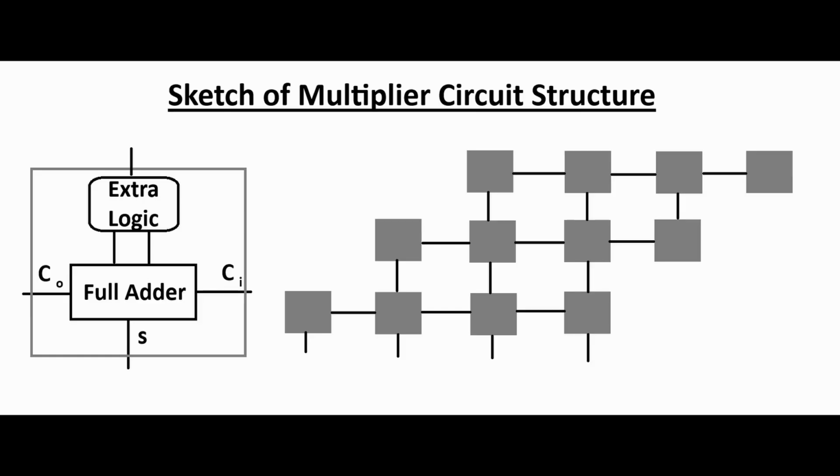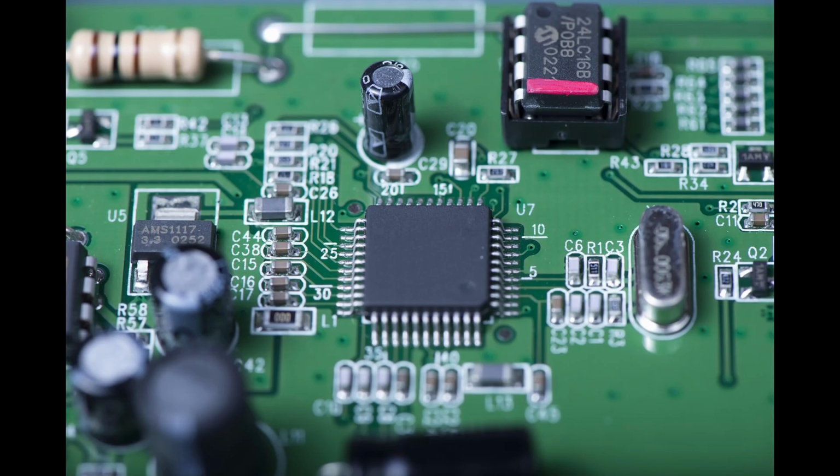We can implement this kind of multiplication process directly in computers using logic gates. However, in this case, we would use binary as the multiplying numbers instead of decimal. In fact, we can also reuse our full adder circuit with some extra modifications to architect an implementation for multiplication. Logic gates are not just used for addition, multiplication, or other numerical calculations in computers. They form the basis for many other kinds of operations and capabilities.